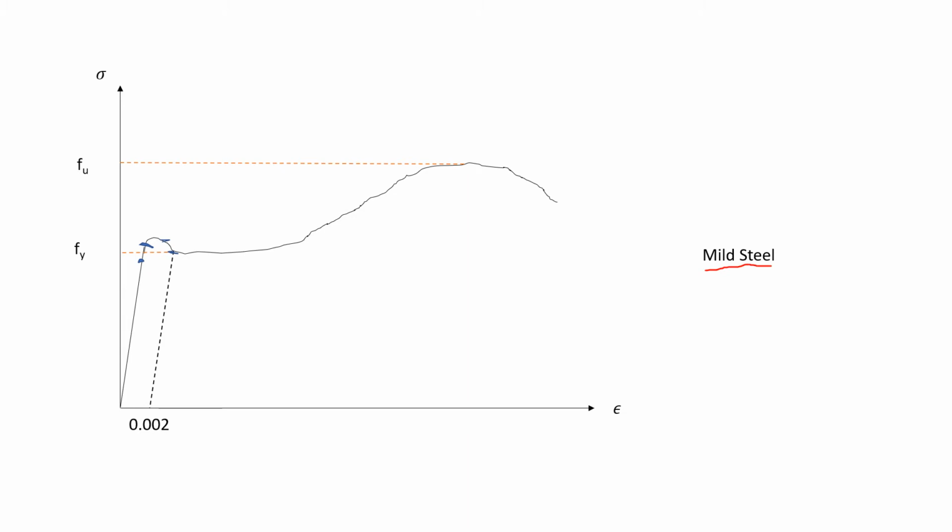Before that, I want to clear one question from a comment. Why are we plotting strain on the x-axis and stress on the y-axis? Let us see, my friend, the quantities which are independent, that means not dependent on another quantity, are generally shown in the x direction. As we know, we are pulling the bar, applying forces, and the dimensions are increasing or decreasing. For a pulling force it will be increasing, for a pushing force it will be decreasing. So that dimension change is shown by what? Strain, or epsilon. That's why we put epsilon on the x-axis and stress on the y-axis. So we have got that point clear.